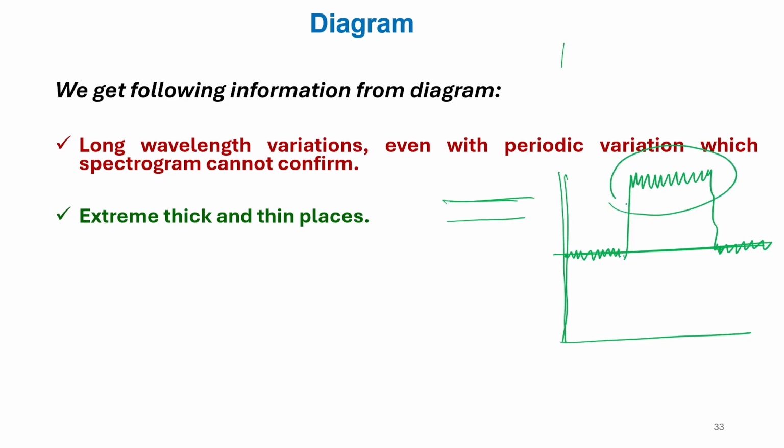Here at this point, if there is a sudden increase in the mass per unit length and it goes on for some time, that means there is a problem at the processing stage where the slivers have been doubled, or it may come in this fashion on the lower side if there is a sliver split. So, from there we can identify the processing performance.